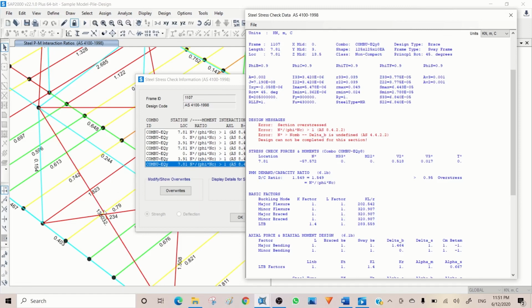So it's not half because this is not very strong. Generally the factor we use for out of plane buckling ratio is something around 0.7 to 0.8. So I will choose 0.75 for the length factor. Both K and L give you the same result.